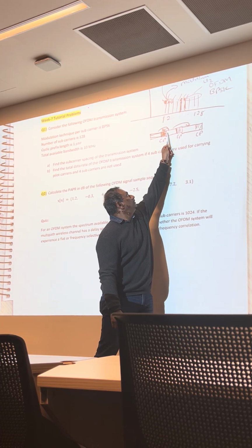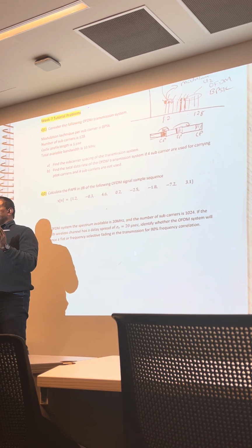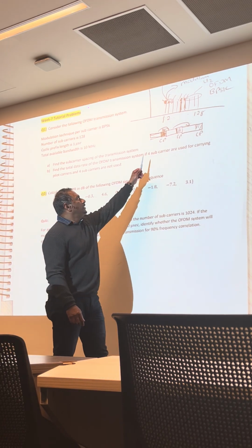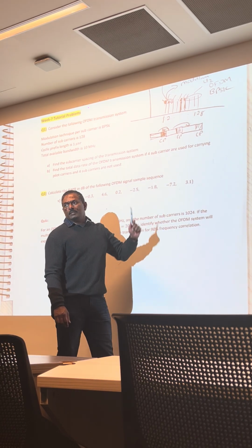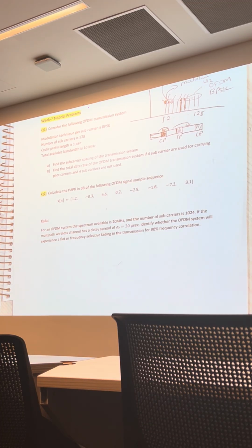This is a copy of the first part of that, and so on. That's why it's called a cyclic prefix. At the receiver, the cyclic prefix is just discarded and only the actual data is decoded. So it's a guard time between symbols, filled in by a copy of the same signal from the beginning.